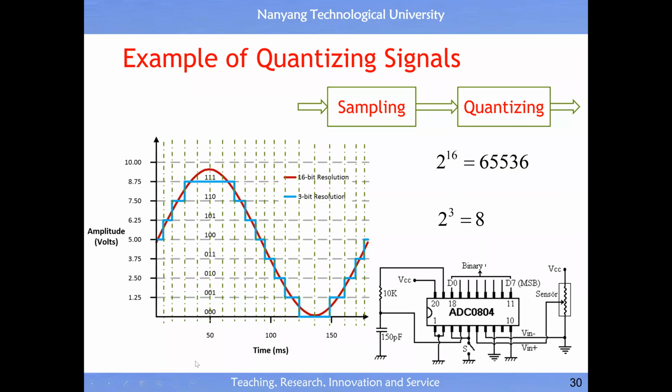Let's say, how do I know this input is 100? First, I predict it is 000. I get the analog value and do a comparison. It's a big gap. Then I do a second prediction, 001. This analog value is very different from this one. I predict the next one, 010, and I get the analog value. You see, it's far away, right?